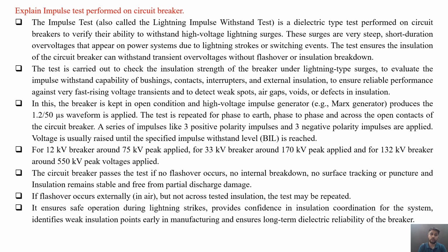The test is carried out to check the insulation strength of the breaker under lightning type surges, to evaluate the impulse withstand capability of the bushings, contacts, interrupters and external insulation. Also to ensure reliable performance against very fast rising voltage transients and to detect weak spots, air gaps, voids, that is deformation points or defects in the insulation.